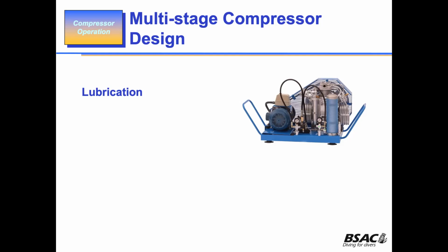But of course, we could get oil past there if the rings are wearing, and we'll soon know about that. That's one of the reasons we have all this filtration. If there is any oil passing over, small amounts of it, it's taken out in that filtration and in those separators.